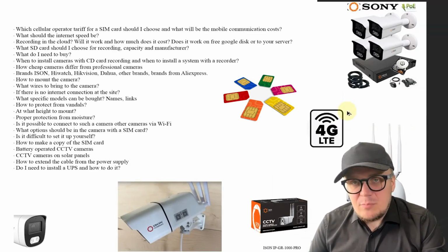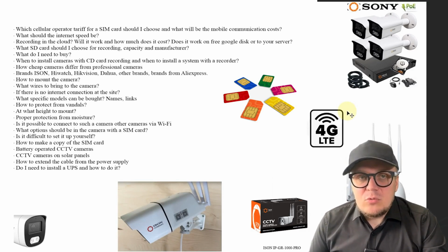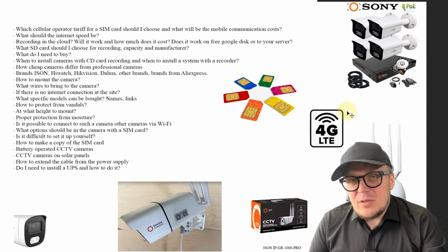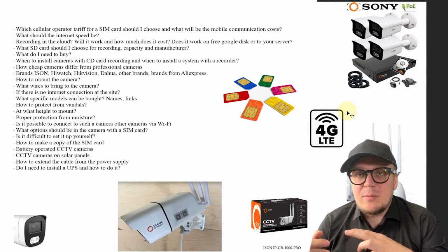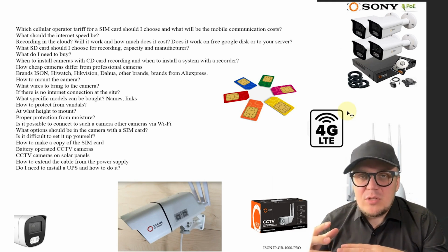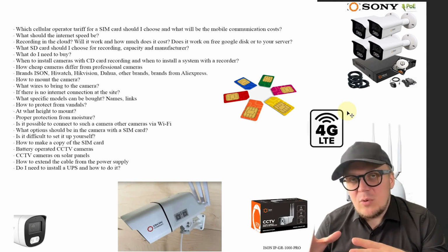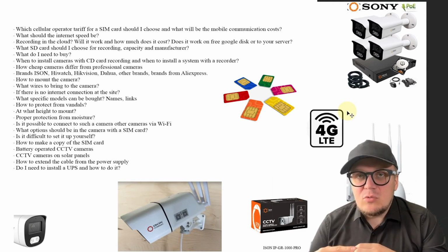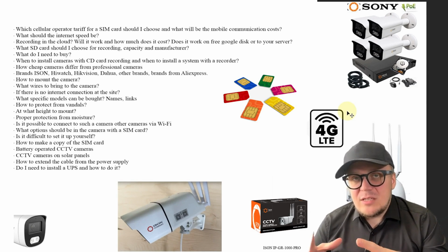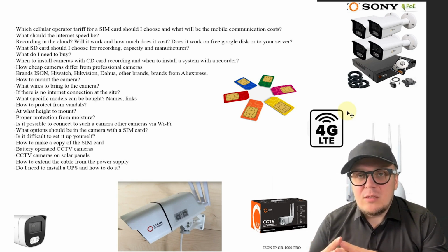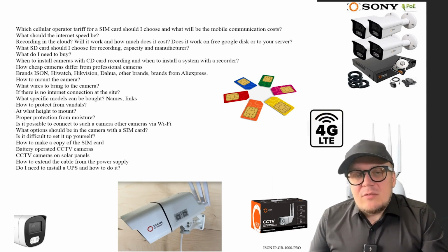If we are talking about setting up multiple surveillance cameras on one network with recording to an SD card, some preparation will be required. Each camera needs to be configured and added to the application. Some manufacturers have their own limitations on the number of cameras that can be added to one application if it's not based on a single video recorder. Therefore, if you're installing 1 or 2 cameras, a more convenient and budget-friendly option might be cameras with 3G, 4G support. If you are installing more, then you need to buy a system with a video recorder, which is how cheap cameras differ from professional ones.